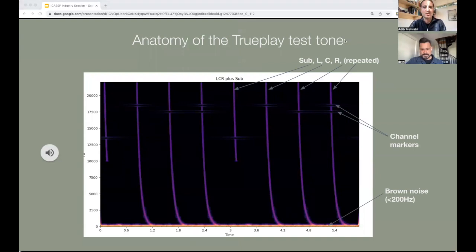Sure, yeah. Here's an example of a stimulus tone that's used in production today. This example shows a tone for a 3-channel soundbar plus a sub, so there's left, center, right, and sub channels. For a given channel, the stimulus consists of three main parts. There's constant periodic pseudo-random noise in the low end, below approximately 200 hertz. There's a train of chirps from around 200 hertz upwards, and gaps in between the chirps that contain no signal above the noise band being measured.